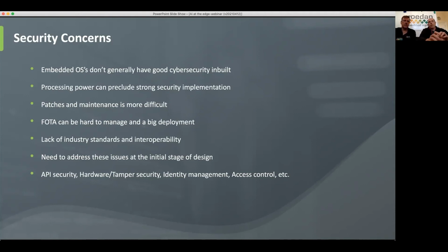You need to make sure that the basics are covered and it's as secure as possible. One of the good things about LoRa is that, because of how it works, there's a very small window of attack from the wireless interface. It sends out a message, and then you've got two one-second windows when you can actually send a message back in.